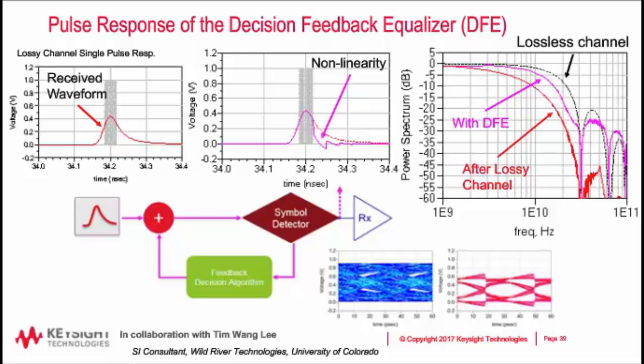And what's interesting, again, if we look in the upper right and we look at the spectral content, the decision feedback equalizer does not actually attenuate. This is all done in signal processing, and it's not attenuating our signal. It's really just adding in a faster falling edge there and adding spectral content in at the higher frequencies. So it's a very efficient method of equalization and correction that can happen at the receiver. The decision feedback equalizer is at the receiver, and the feed-forward equalizer can actually be done at the transmitter.